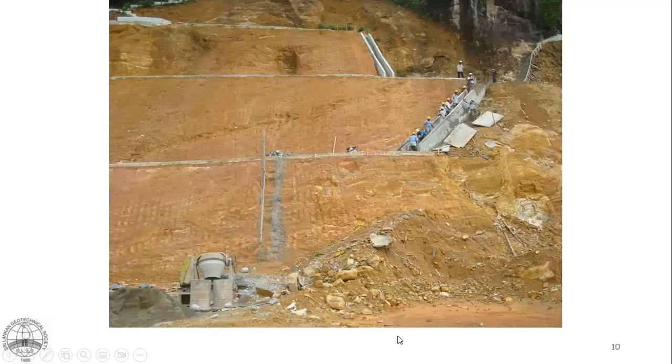This is another location where drainage was given a lot of attention. So there's a further high slope up there. There was a lot of water coming through that. So they have it in 3 berms, right? So that water is directed through this cascade drain to the berm drain, and further cascade drains are there. And so this is halfway through the